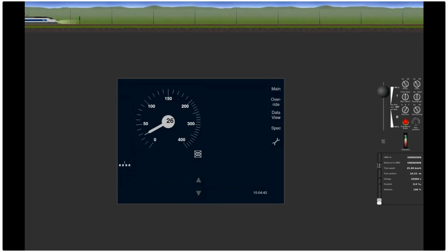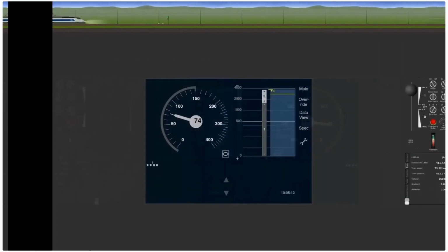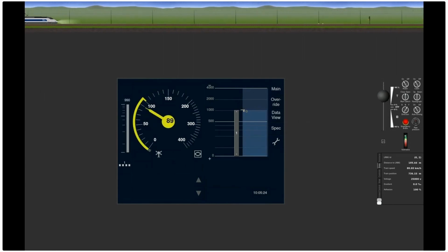The train starts in staff responsible mode level 1. It receives the first movement authority when passing the first balise group. The next passing balise group will announce an unprotected level crossing with an order to stop in rear of the level crossing area. The onboard system calculates a braking curve to force the driver to stop in rear of the level crossing.